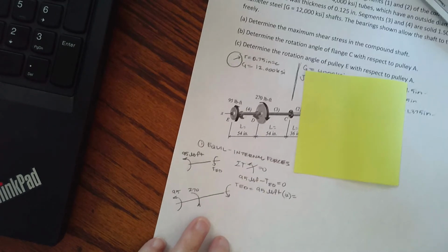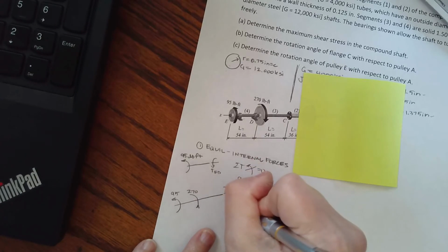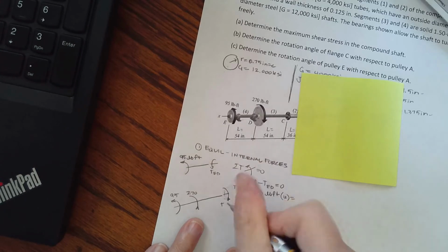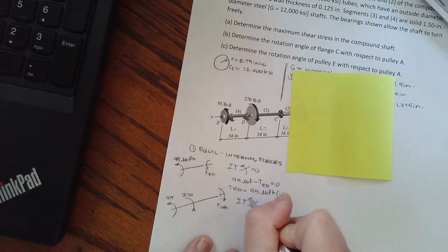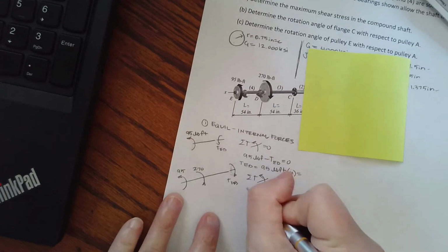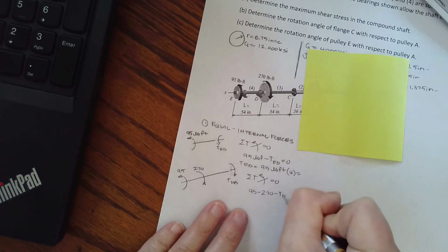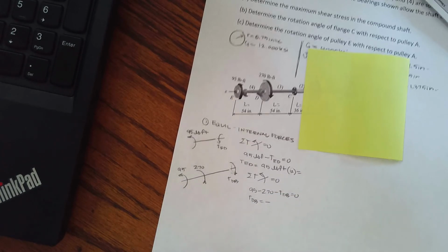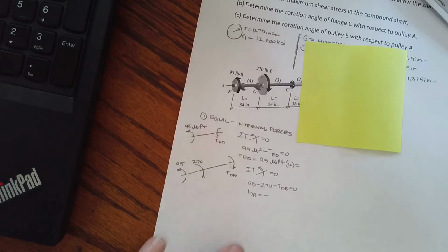And I guess maybe I should make them so they look the same kind of direction. So coming back towards me is positive. That is going to be torque from D to B. So now let's sum our torques. I'm going to call that direction positive. So I have 95 minus 270 minus torque DB equals 0. So my internal torque DB equals negative, okay, negative 95 minus 270, negative 175